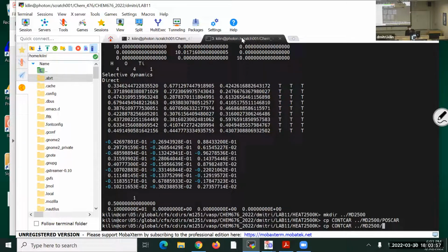Yes. What do you mean fix atoms? Yes, absolutely. So if you change letter T to letter F, it will freeze certain degree of freedom. If you freeze all 3 projections, you will fix a given atom. It will work both for heating and for molecular dynamics.